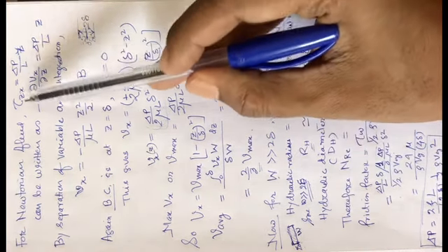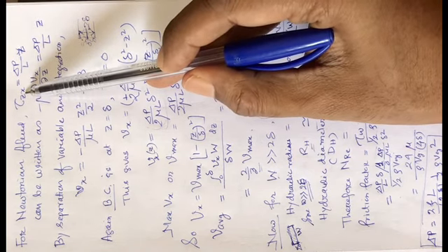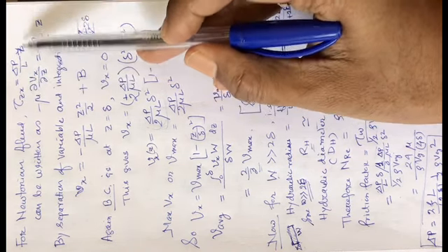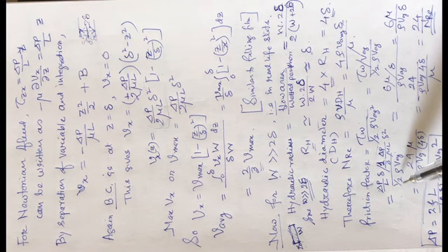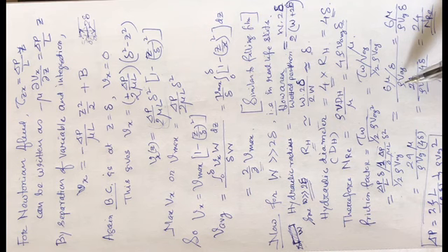You see, wall shear is when z is equal to half thickness. So then delta P by L into the half thickness. Okay, so then the denominator is half into rho V average square. So this leads to 6 mu by rho V average into delta, which is 24 by rho V average into 4 times delta by mu, which leads to 24 by NRe. So then you can estimate the friction factor for this particular slit flow as well. That is equal to 24 divided by Reynolds number.